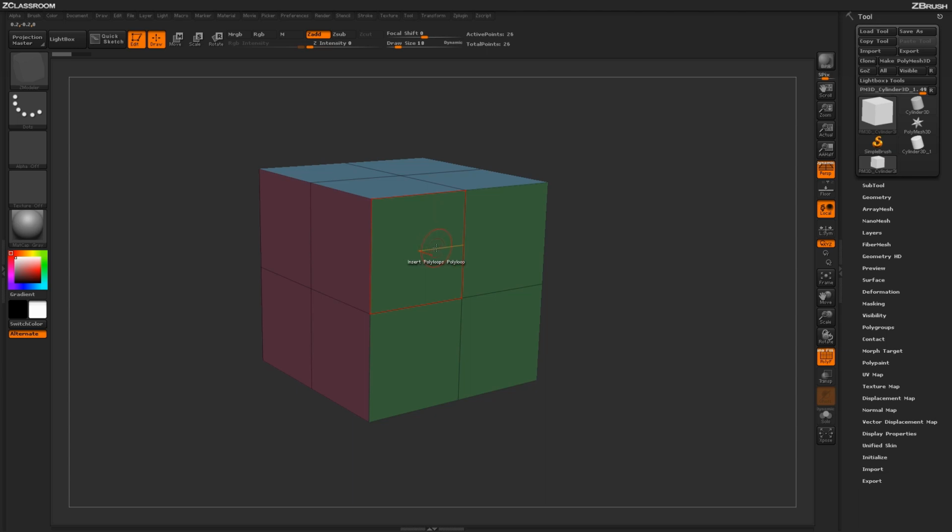So to apply the action, just simply click, and you will notice that you will get an edge inserted into the center of that poly loop. If I undo that process, and now instead of just clicking, but rather click and drag in a vertical fashion, you'll notice that I will get an increasing number of edge loops. While doing this process, if I go left and right instead of vertical, I will also get a bevel effect that will be applied directly around that poly loop. This will allow you to create nice rounded surfaces.